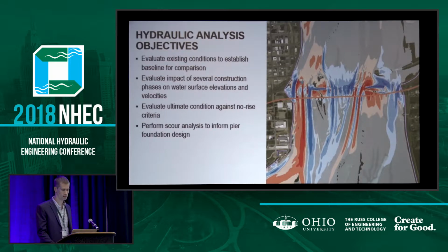So to do that, we had to establish an existing condition. We had an ultimate condition model, and then we also had to model temporary conditions because this project spans more than one construction season. They also use the results to inform the foundation design, so the scour analysis.